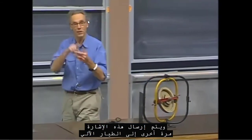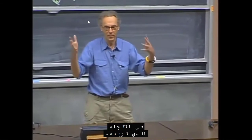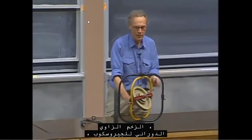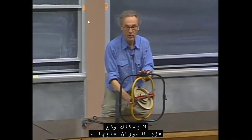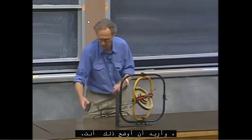And that signal is being fed back to the automatic pilot, and that keeps the plane flying in the direction that you want to. So you use as a reference all the time the spin angular momentum of your gyro, which is now mounted in such a way that you cannot put a torque on it even when the plane changes direction. And I want to show that to you.